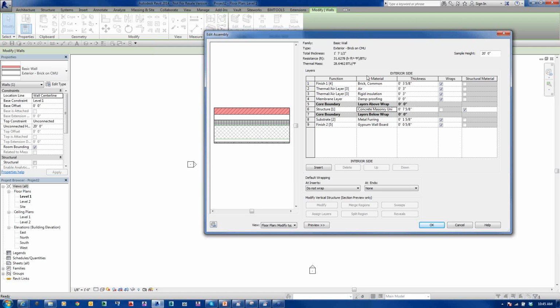Again, take it with a grain of salt. I tend to round down for those materials, or I'll verify against what I'm looking up in a standard code book, saying, okay, if I have a 2x6 wall that's insulated, and I have a stone exterior and gypboard and maybe a 2-inch layer of rigid insulation, what is that typical R value? Okay, I'm in the ballpark. Maybe if I need that value, I'll list the one from Revit. Maybe if I'm okay, I'll list the one I get out of the manual or the book process.